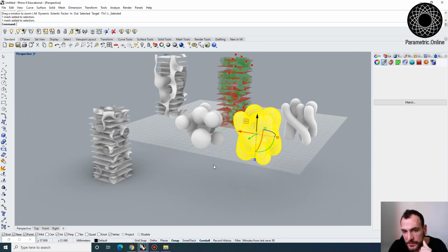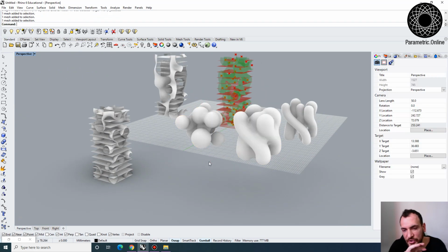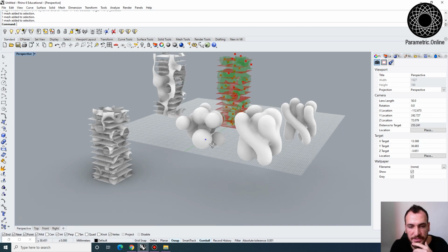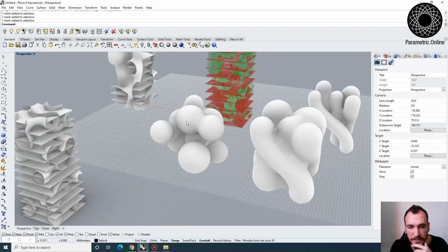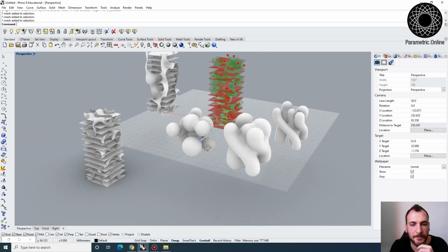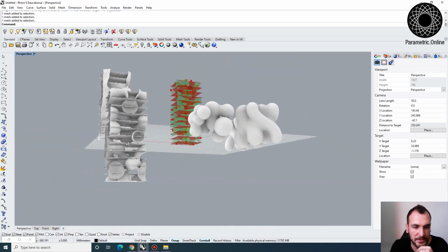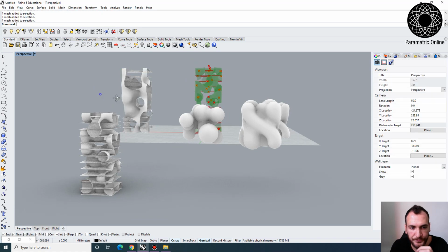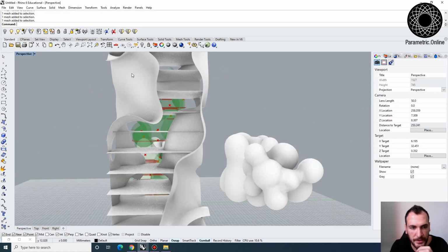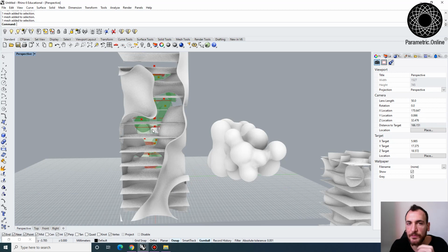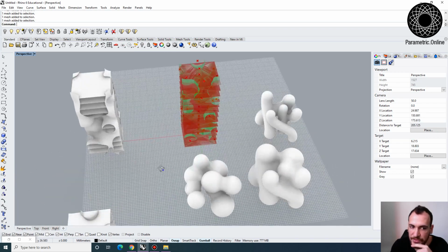So you can work with the curves, with the points. I try to do one or the other, because if you try to connect them, then the mesh refinement shows sharp transitions. It works better if the geometry input is similar. So in that sense, you can use points and curves and try to get a nice smooth surface, and then do something with that. You can also intersect it with other meshes or planes, and define slabs or other types of surfaces in it too.